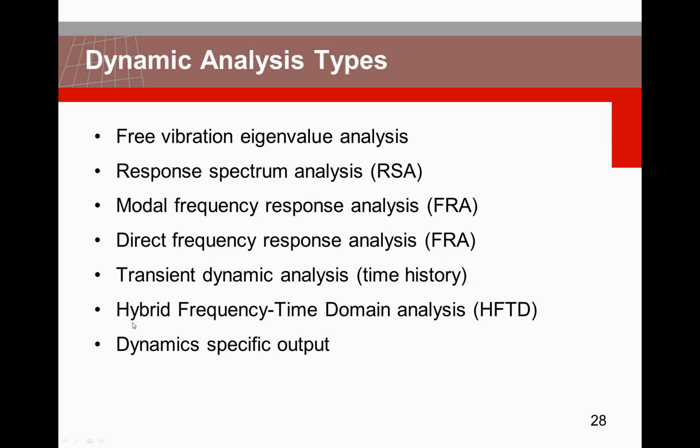We have in DIANA a hybrid frequency time domain analysis, which, as we'll see, makes it possible, for instance, to have some frequency dependent behavior in a time history analysis. This makes it possible for dam analysis to do, say, cracking or interface behavior, which is nonlinear, which you want to see in the transient dynamic domain, together with compressibility of the fluid, which is a frequency dependent behavior. How this is being done, I will briefly explain in the HFTD method. And then we have a little bit of information on dynamic specific output.